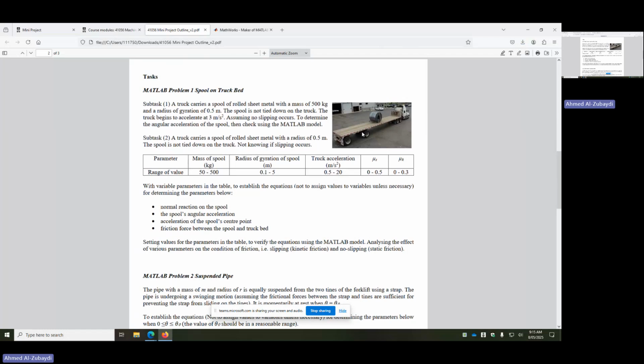So they learned the lesson later, and they changed the braking system to something we call the clutch brake system. If you would like to move, you apply the power to disengage the brake and engage the clutch, and then the movement starts. If something happens or you cut off the power, it works in reverse. The clutch will be disengaged, but the brake system will be applied, because it's not only about disengaging, but also about stopping the movement.